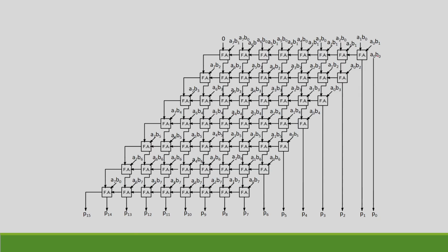We can see that A0 B0, I am not showing the AND gate here. So, total I am using 64 AND gates to generate all the product terms. So, this is generated through AND gate with A0 B0 as the inputs, output is A0 B0. So, this itself is your P0. Okay. Then P1 is, as I have told, A1 B0 plus A0 B1, the third input here I have not shown, this is 0. Okay. For all this is 0, this is 0.